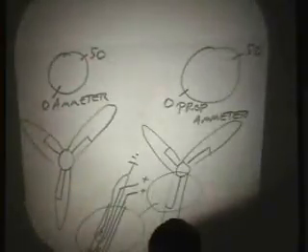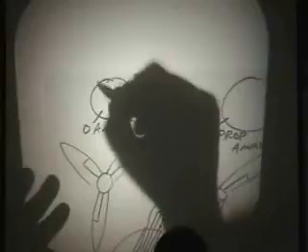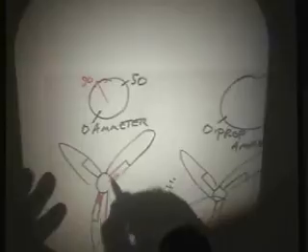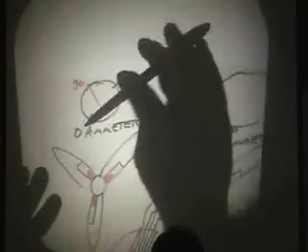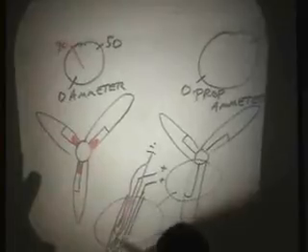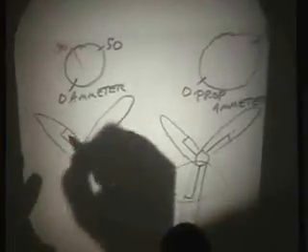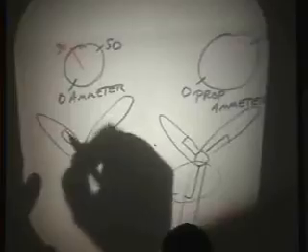When we turn this system on, one of the propellers is going to come on. Let's say we turn it on, and we see this ammeter go up to 30 amps. The inside heating element is going to be on, and it'll stay up there for about 30 seconds. Then it'll come down to 0 for a second or two, and then it'll come back to 30, because now instead of sending electricity to the inside, it's sending electricity to the outside. So now the outside heating element is going to get hot.